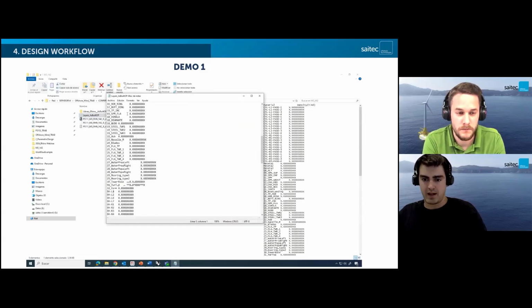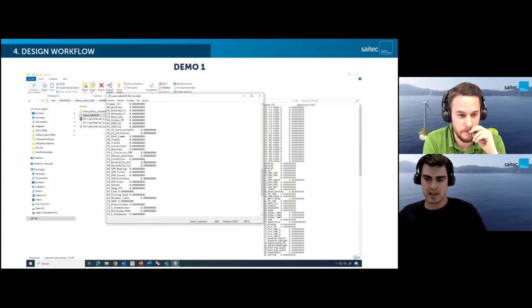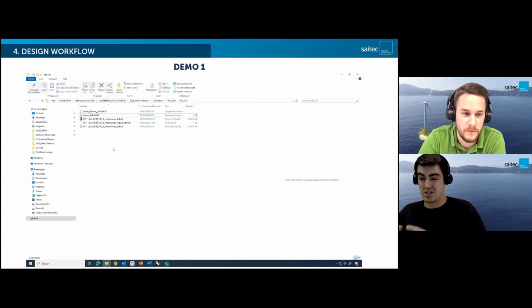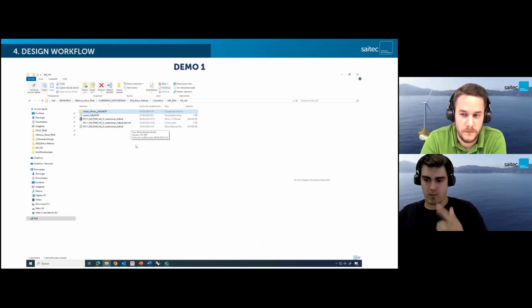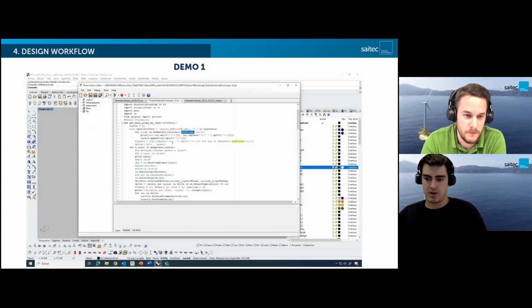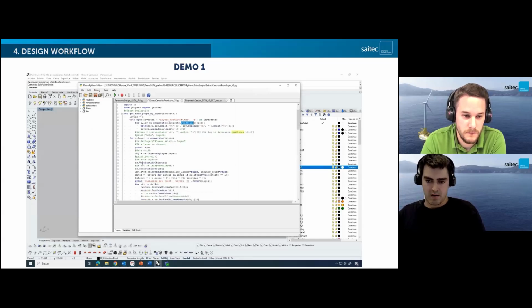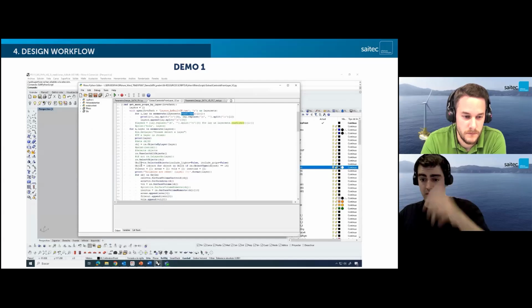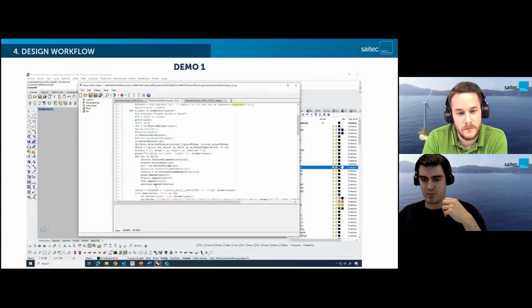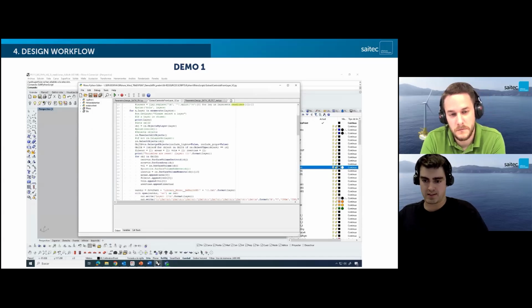Usually here we have the densities for reinforced concrete, primary steel, or also adjusted densities for the known weights, such as the turbine or the electrical equipment. But in this case, as it is as-built, we adjusted the densities with measurements obtained in the tests carried out during the construction. And what the script does is select these objects for each layer and extract the physical properties that are of our interest.